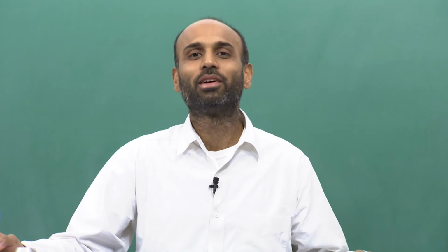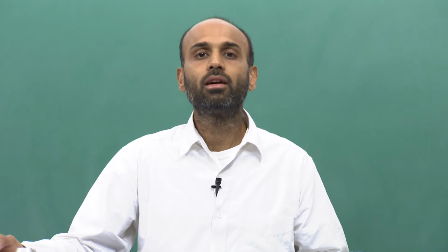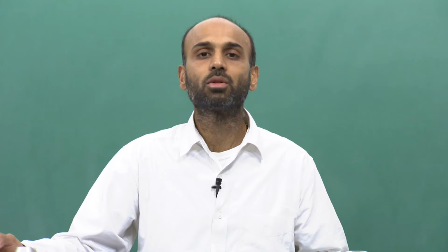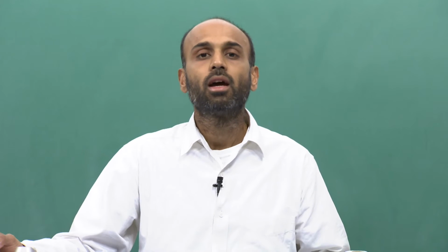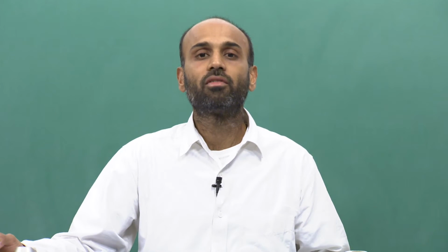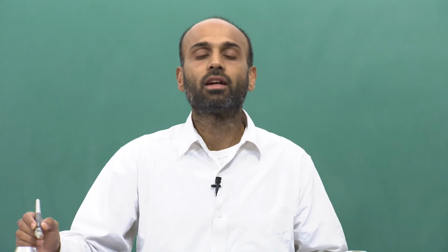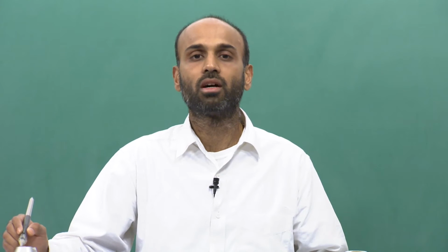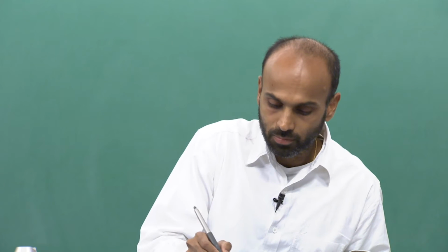Welcome to another module in this massive open online course on MMSE estimation for wireless communication systems. So, we are looking at the linear MMSE estimator, that is the linear minimum mean squared error estimator, also known as the LMMSE estimator, and we are looking at finding the optimal weighting vector, that is the combining vector C bar. We said that if we have a function f of the vector C bar, then the derivative with respect to C bar,